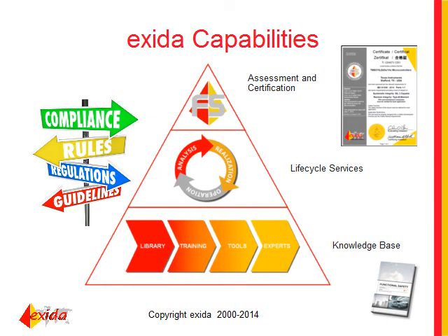Now, as far as a regulation, that ISA technical report is an informative report, which is very useful and provides a lot of insight, but it's not a normative report. It's not a requirement. The normative part would be IEC 61511 or 61508, but the technical reports are very useful things to try to get an understanding.